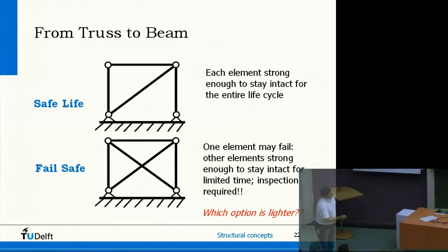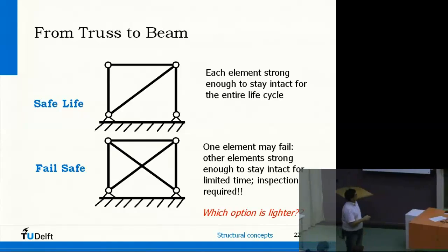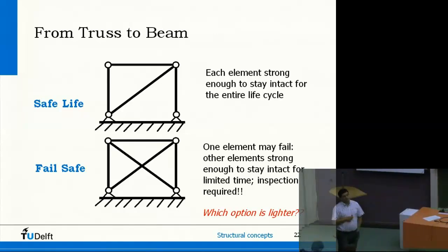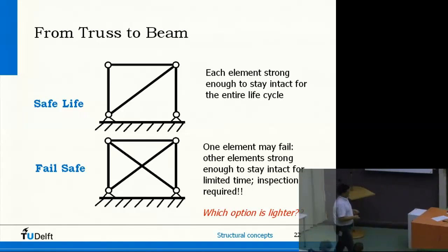Most of the structure nowadays is designed with this concept in mind. There are a few items, like undercarriage for instance, that are still designed in a safe life philosophy. You cannot make that redundant. You only have one nose wheel for instance. You are not going to do it twice. So there you have differences in design.